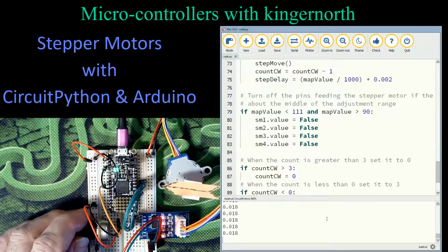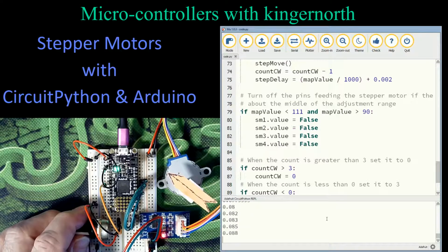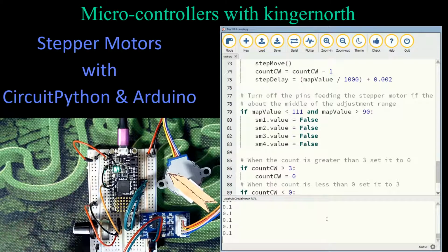And we have pretty good control over this. So it's not a hard program to go through. Basically what you want to do is you want to take your pot. The basic steps are take your pot, remap it into a more usable range, because the inputs are usually much higher range than what you really want for something like this. Then you want to create your step pattern, and that's what's created in the subroutine. In either case, it was created in the subroutine, doesn't matter which program.